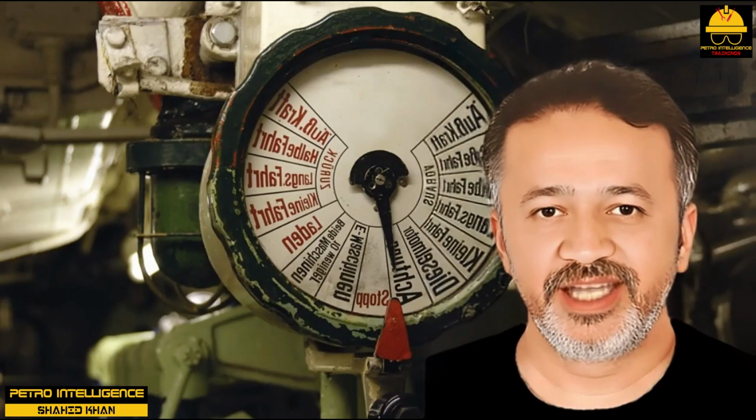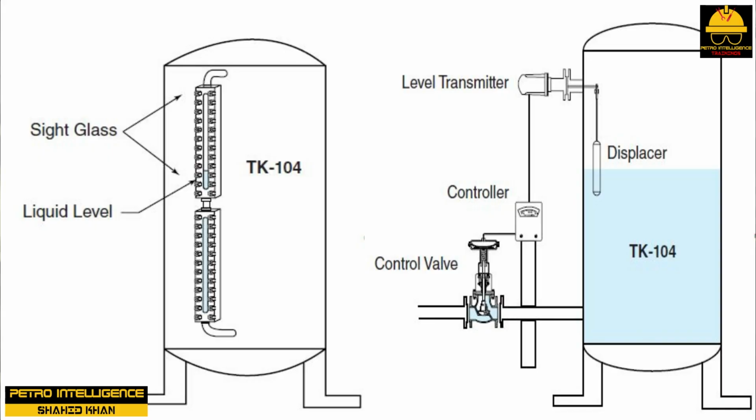Direct level measurement instruments. Direct instrumentation is in physical contact with the surface of the fluid. Direct level measurement equipment may calculate the product surface level from a specific point of reference. Direct instruments include sight glasses, floats, displacers, and probes.